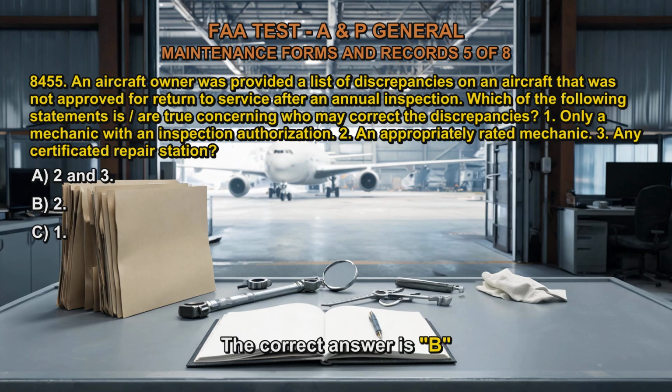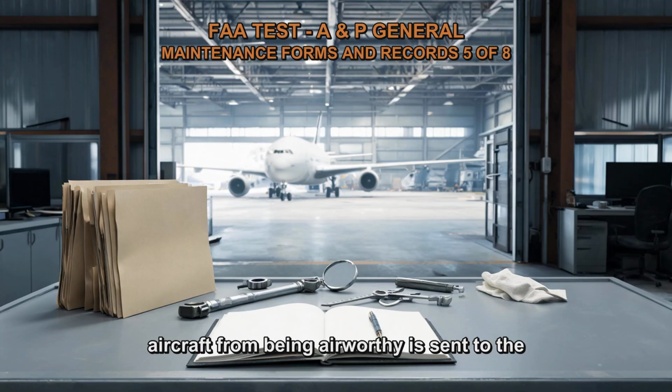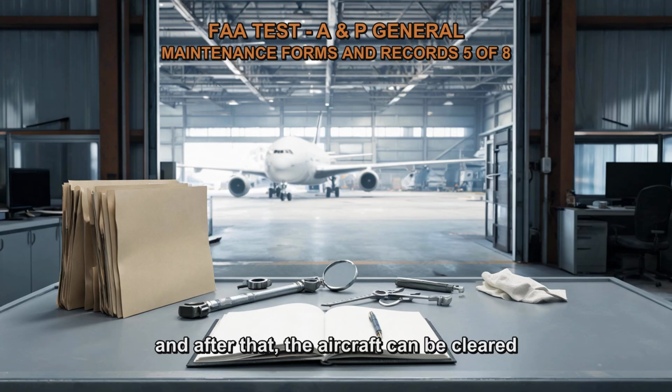The correct answer is B. A list of the deficiencies that prohibited the aircraft from being airworthy is sent to the owner or operator of the aircraft if the return to service of the aircraft was not authorized following the yearly inspection. A suitably qualified mechanic can resolve these inconsistencies, and after that, the aircraft can be cleared for operation again.